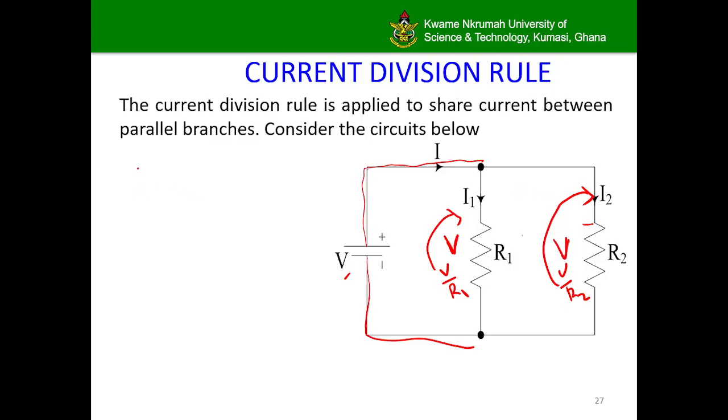The value of V is the total voltage of the circuit, and so it is the total current, or the current leaving the source, times the total resistance. The total resistance of the circuit, since there are only two resistors, R1 and R2, and they are in parallel, is equal to R1 R2 over R1 plus R2.